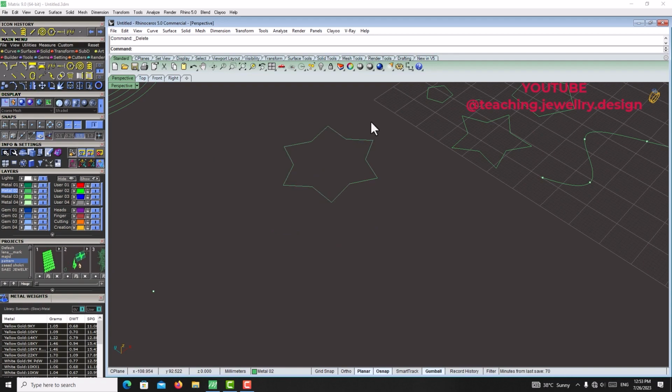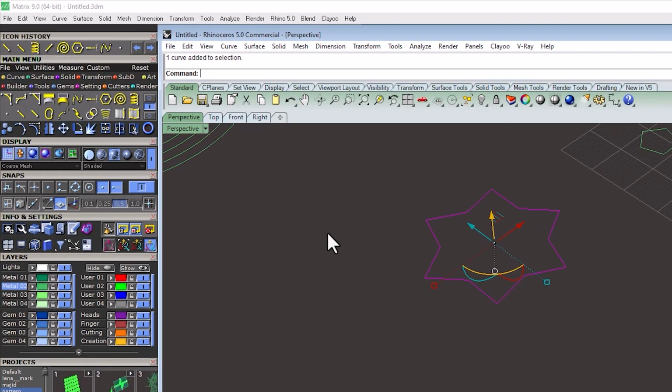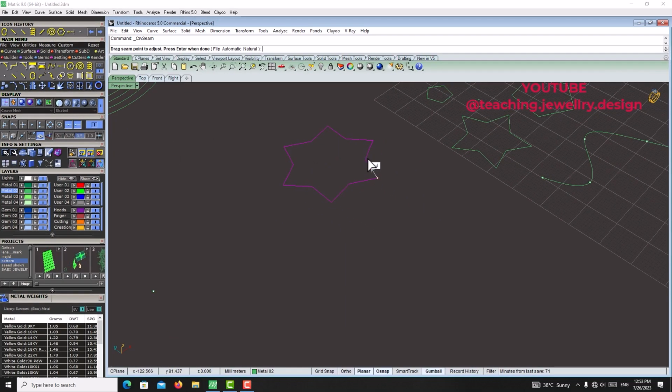When you have a line and you want to split this line into many sections, two, three, several, or many sections, you can use these icons. For example, I draw a line. I want to divide this line into 4 pieces with 3 points.